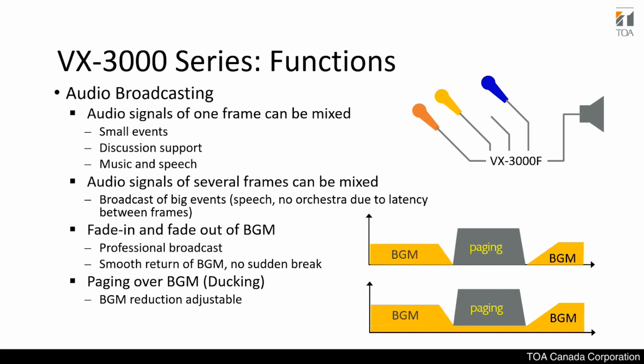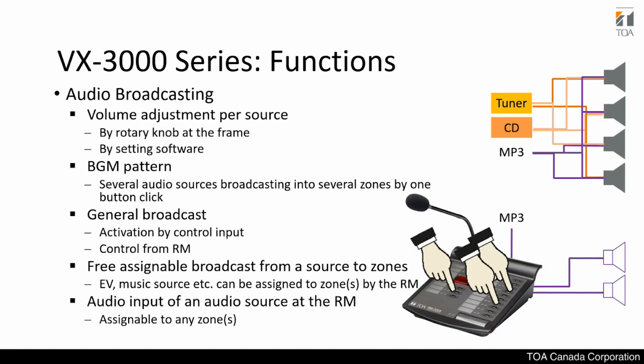For public announcement, there's of course paging involved. There's the option to fade in and fade out the background music while paging, and also ducking when paging the particular zones. Going further with audio broadcasting, you can route, as mentioned earlier, any source to any output. You can adjust the gain of the source by adjusting the rotary knobs that I showed earlier, or setting it on the setting software that is available for the VX3000.